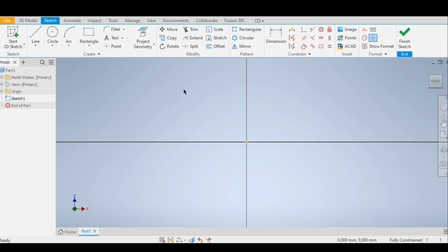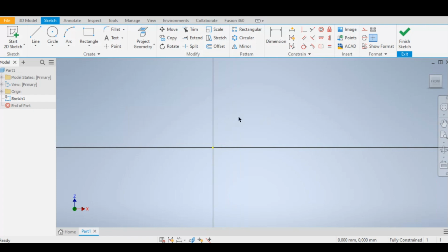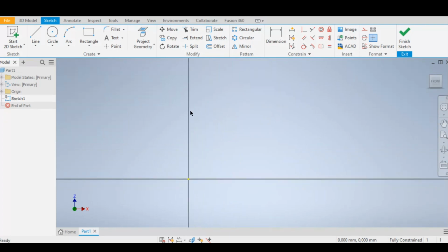To start our sketch off, you can see we've got our orientation correct now, and from this we can simply start the sketch. So follow along throughout this tutorial, because we are not only going to sketch a 2D sketch, but we are going to add extrusions to give the sketch some volume, and then we will do a cutout extrusion to show you exactly how to manage your extrusions in Autodesk Inventor. So let's start off to draw our simple drawing here.